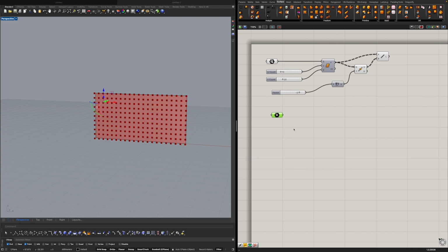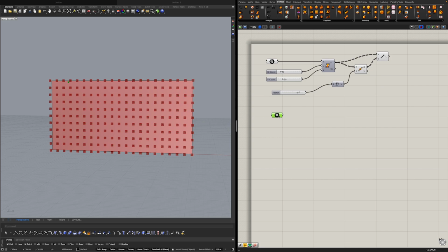If you're familiar with vectors, you know that they are on geometry and you cannot see them. We are going to create a vector from this point to the surface frames we have. So for that we want vector between 2 points. Here you can see we have 3 inputs. We just need 2 points, right? Point A, base point, and tip point. So base point will be the new frames, and the tip point will be the point we just created.